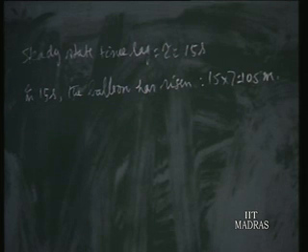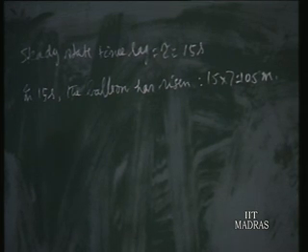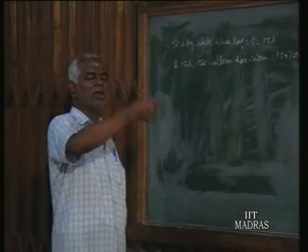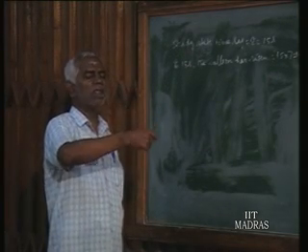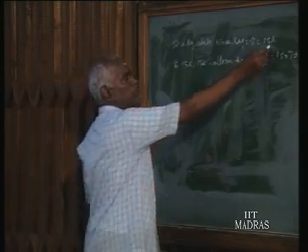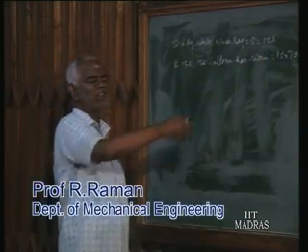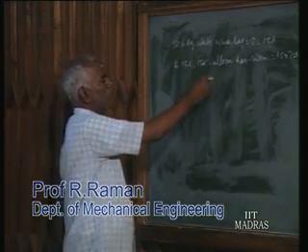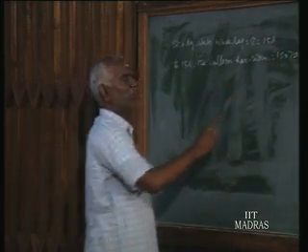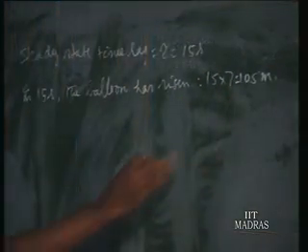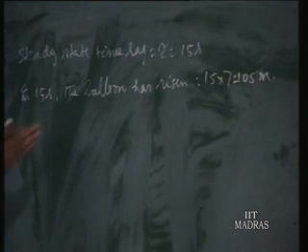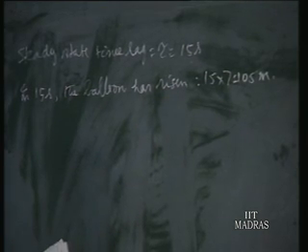Now we know that the steady state time lag is equal to tau. So whatever reading we get was taken one time constant earlier, that is 15 seconds earlier. Where was the balloon 15 seconds earlier? It is rising at 7 meter per second, so in 15 seconds, 105 meter. So 105 meter below, this temperature of minus 1 degree centigrade was shown.